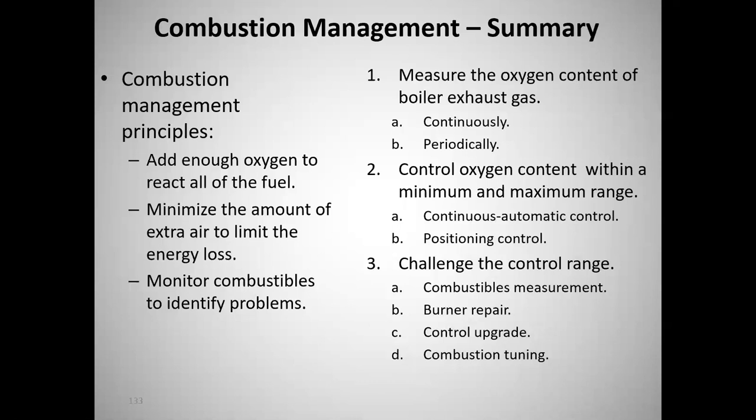You go in a plant, you stick your combustion analyzer in the stack, and you measure 7.5%. They're burning natural gas. And yeah, guys, this is not real good. Of course, you have to look at the boiler load. If the boiler load is 25, 30%, that may explain part of that, because at lower boiler loads you have less turbulence, you don't have as good mixing, and you have to make up for that by putting in more combustion air.